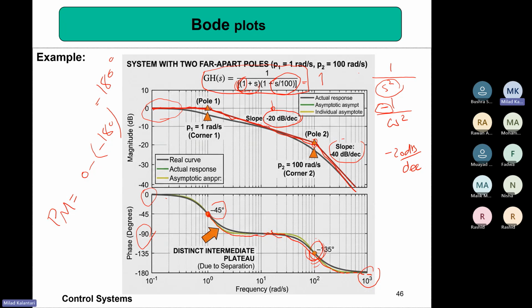On the other hand, we can also go back to high frequencies, or the frequency at which the phase is 180 degrees, but we check the gain. There is another way also. So we go here where the phase is 180 degrees, but how about the gain? The gain is pretty low, right? Negative 40 dB is 0.00 something, which is too low.